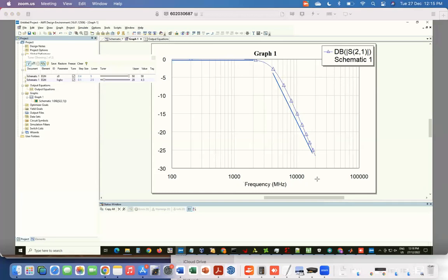The reason I'm showing you this is that you'll often see this kind of graph. There is a very nice flat response up to the cutoff frequency, and from the cutoff frequency onward, there is a linear drop off. So this is that dB per octave kind of thing. What does that mean here in log units? Every time the frequency gets scaled by a certain factor, or let's say doubled, the loss will increase by a certain linear amount in log units, which in regular units means it changes by a certain factor. So this is graphically visualizing the same aspect of that filter.